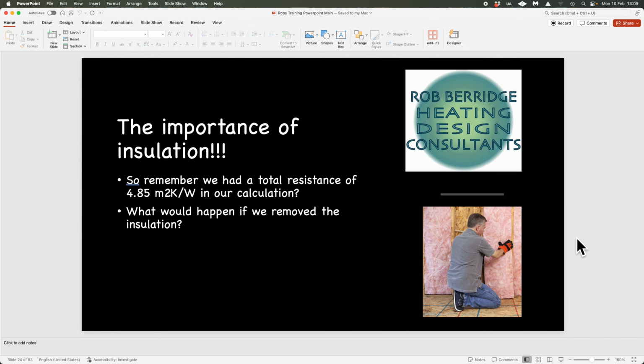You will lose less than a couple of handfuls of the polystyrene balls, but you push that into the cavity, and push it all around so that maintains the integrity of that insulation. And then you can drill your second lot of core out, and then you've maintained that right the way through. So a real good tip to do that and make sure that you keep the heat and maintain the resistance value, the R value, of that typical construction.